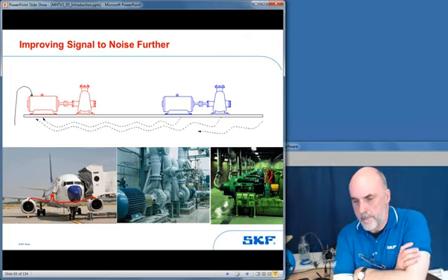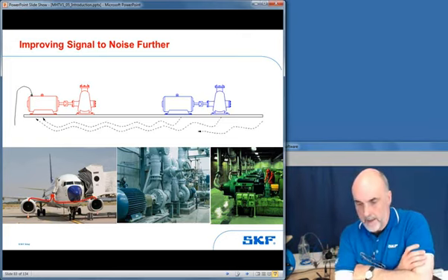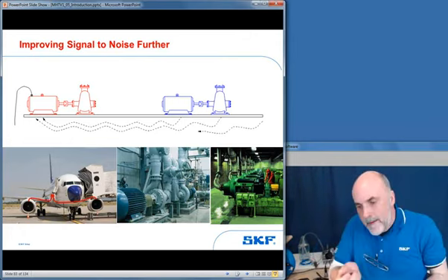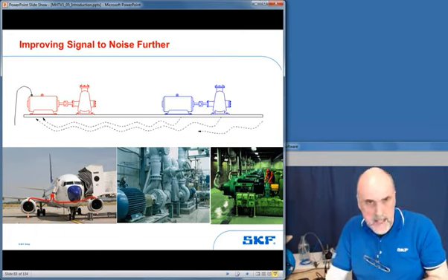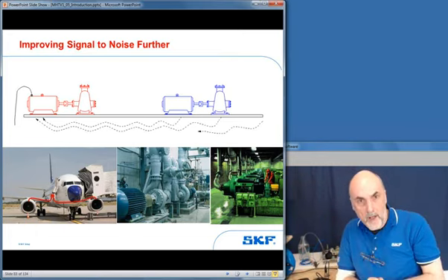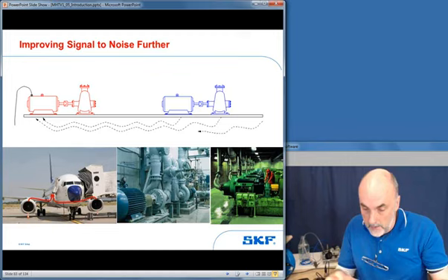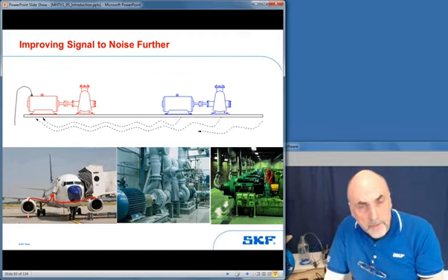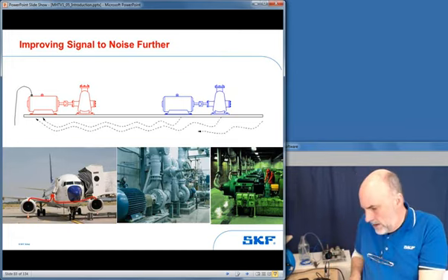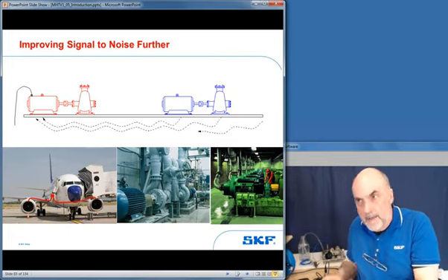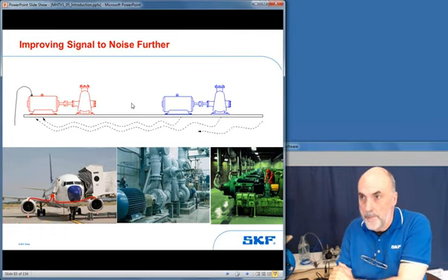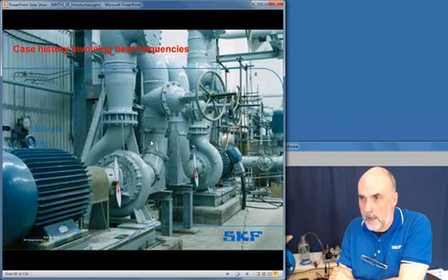I was on an oil platform many years ago. I was in the ventilator fan room. I had my hard hat on, my ear defenders on. I was taking readings off a machine and writing them down. And when my eyes got used to the gloom, I could see that the shaft wasn't rotating. I was taking readings off a machine that was stopped. And yet when you put your fingers on it, you could feel your fingers tingling. And it was a classic example of how vibration can transfer through the structure and pop up.